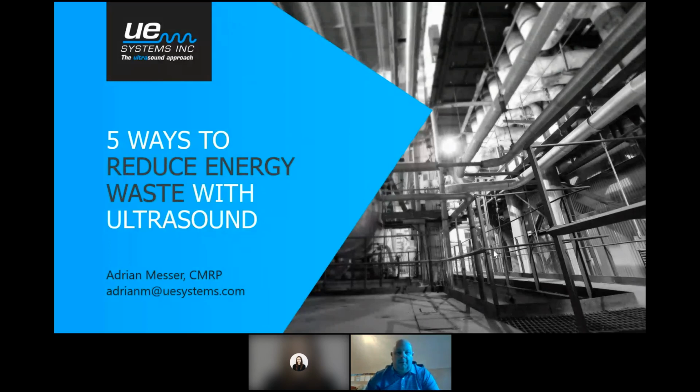And that's really critical with not just energy conservation initiatives, but with any maintenance and reliability initiative. Anytime I'm in front of a group of people talking about ultrasound and maintenance and reliability, I always say, in all of my visits and interactions with people in the industry, if there's one thing that maintenance and reliability professionals can do better, it's reporting and documentation, really just showcasing exactly what it is that you're doing. And anytime we can put a dollar amount to that, people may not understand, hey, we went out and we found 40 air leaks today, but they may understand, hey, we found $10,000 in air leak waste today.